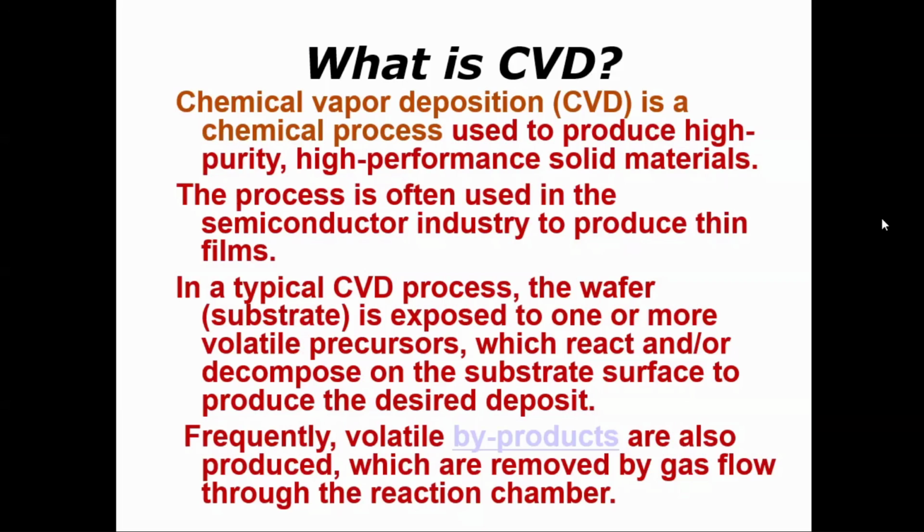So the phosphorus atom approaching the substrate will see the vacant site, and the phosphorus atom will move into the vacant site, and then it will form a bond with the silicon atoms on the surface. Fine. So wherever there is a vacancy, there in that lattice site the phosphorus atom will sit, and then after that it will form the bond.